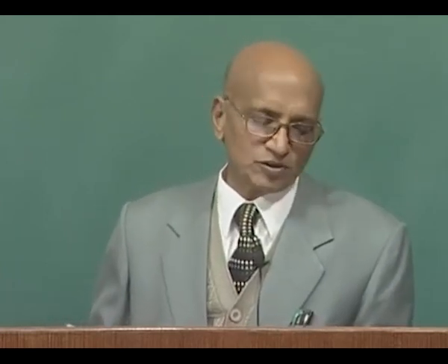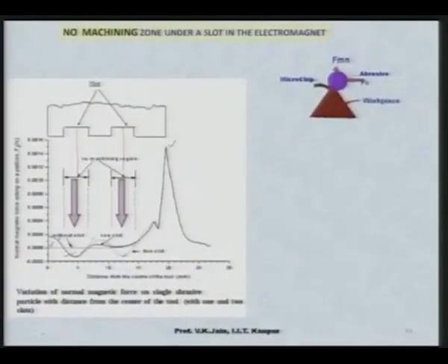So, at the most you can have 2 slots, but generally 1 slot only is used to enhance the performance of magnetic abrasive finishing. And this is the highest force that you are otherwise also going to get at the edges of the electromagnet, and this contributes a lot as far as finishing is concerned.